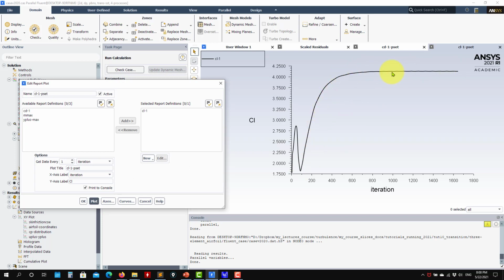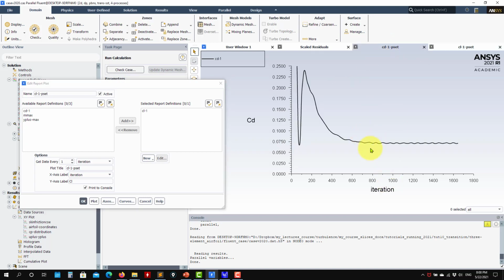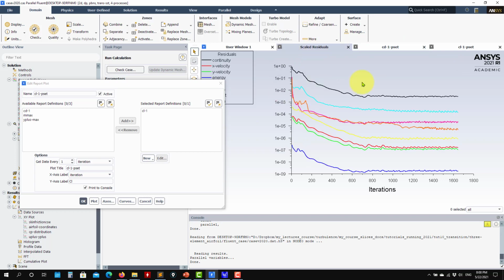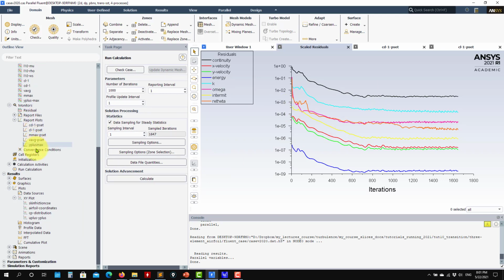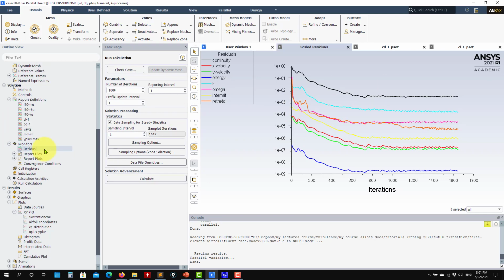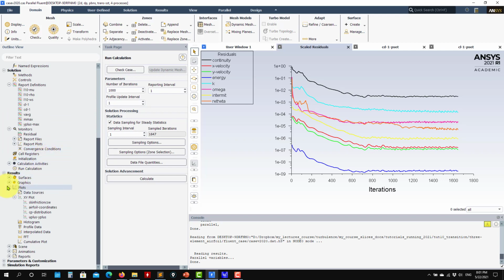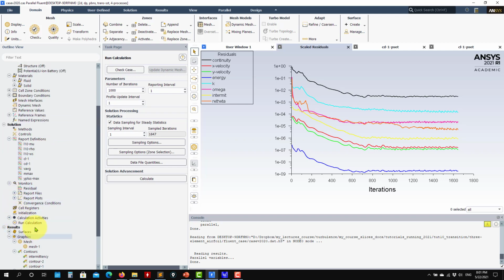The residuals got stable at about 1000. See that they are not necessarily stable at the same value; one gets stable, and the other will get stable later. So there is kind of a phase difference there. That's why you need to monitor many things at the same time. I didn't save the other values, so I don't have that information available. So this is how you run this case. It will run very smoothly, and now we can do our traditional post-processing.